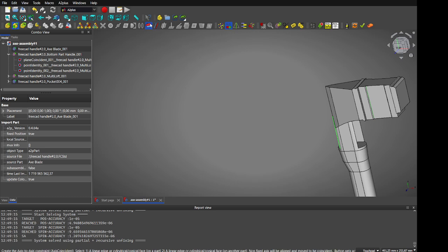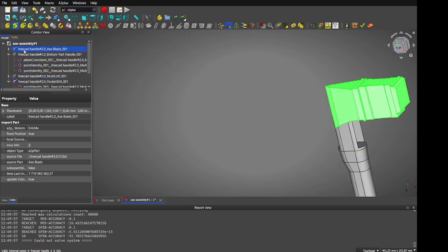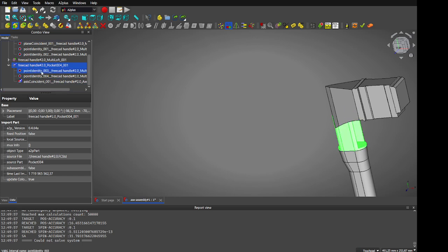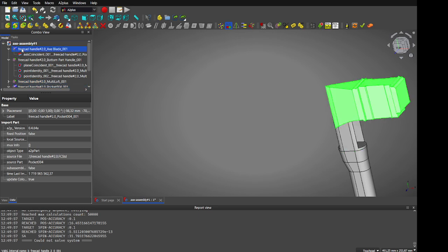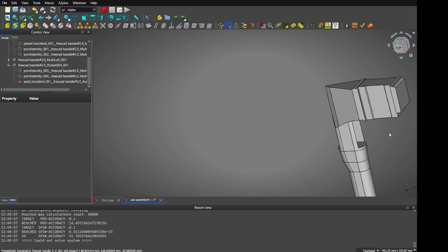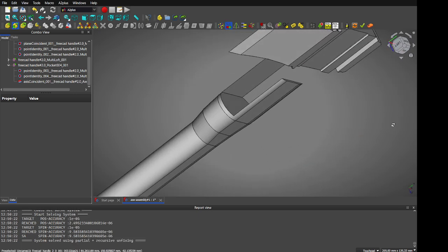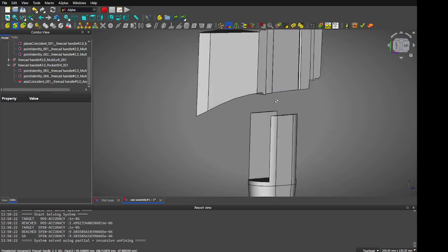Now use the axis coincident constraint. An error happened, so one of these parts must be selected as fixed, or 2 are selected as fixed. So switch this fixed to here, unselect, and here select as true, and refresh. Now it is in one desired axis.